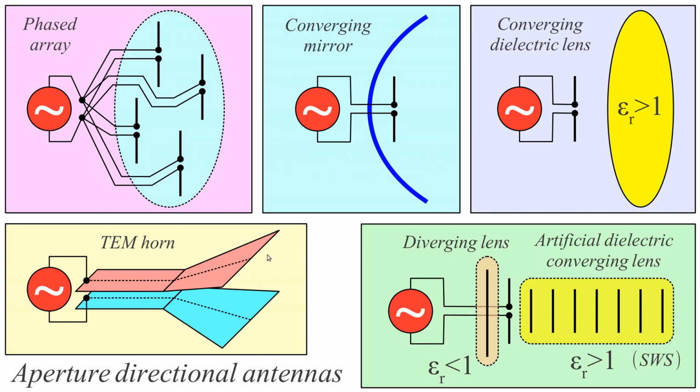This horn is also the so-called idiot antenna because the horn always radiates. Horns always work. This is an antenna that always works. But this antenna may become very large because the Rayleigh distance may be very large, and we may have to build very, very long horns. Note that for a given aperture, the horn may become very long. For instance, for satellite television reception, a dish is nowadays around half a meter in diameter. If we were building a horn, it would be half a meter aperture for 10 meters length, and that becomes a huge antenna. It works, but it's just impractically large.